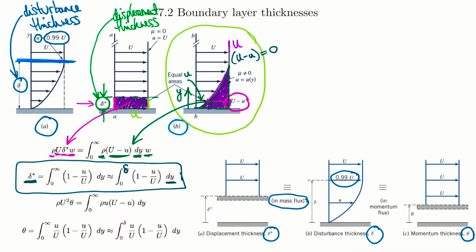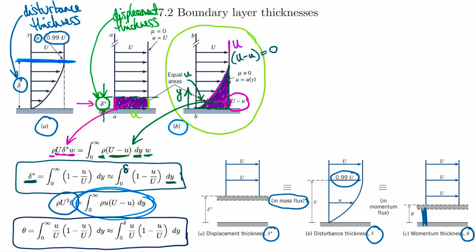And so you define that mathematically in the exact same way, where you can say, what's the momentum flux across this region here, right? Versus the momentum flux decrease that was caused by the fact that there's a boundary layer. Rearrange that again, and that's how you can practically calculate it. Generally, that's done with experimental data, I'll note as well, because it's quite complicated to get meaningful values for this. So that's how you would go about calculating a momentum thickness. Much, much more important for us to just focus on the idea of what displacement thickness and momentum thickness are. What does it mean?